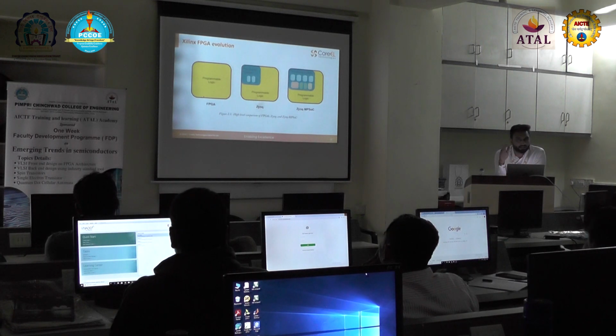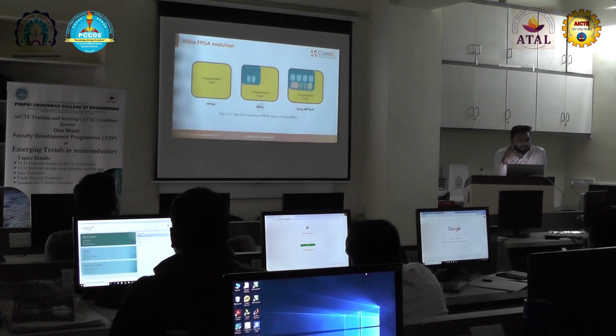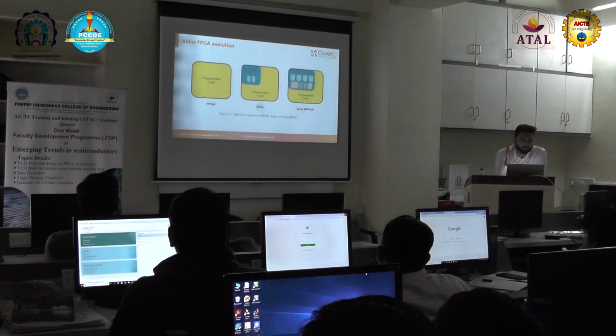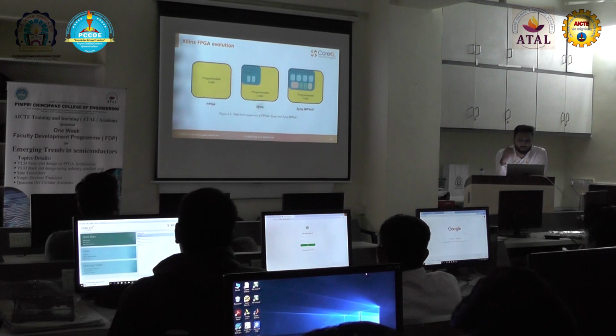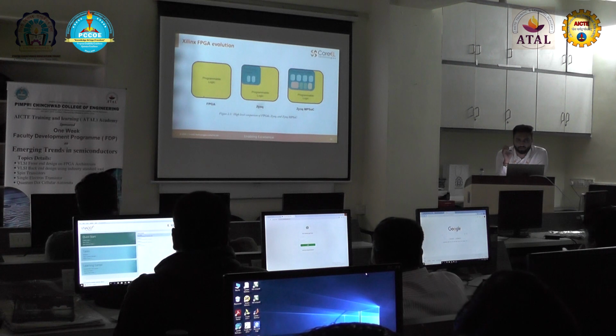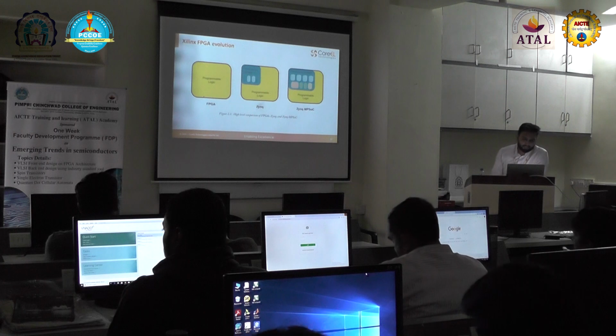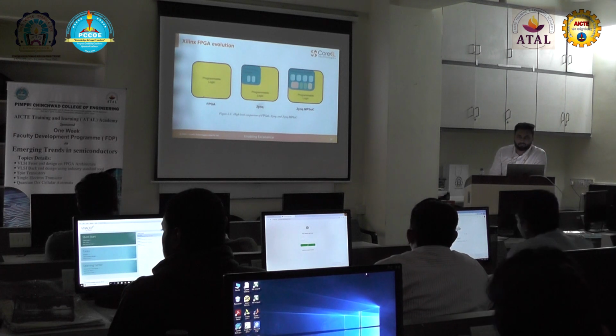After FPGA to Zynq, Zynq to Zynq UltraScale. If you require only the FPGA, meaning the programmable logic part, then you go with an FPGA like Artix-7, Kintex-7, or Virtex-7. If you want some more processing system and a large amount of PL, programmable logic, then you go with the Zynq. When you want more PS and a smaller amount of PL, then you go with the Zynq MPSoC. This is all about the evolution of FPGAs.